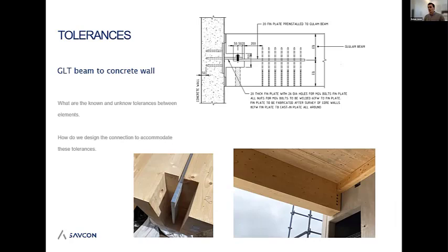So when you have that, if that core is out by 10 or 20 mil in a north direction, you're also now out that 10 or 20 mil in the south direction. In one case, you're going to be shortening a gap, and in the other case, you're going to be elongating the gap. So it's how do you build this tolerance to be a 2-way tolerance, both a positive and a negative case.